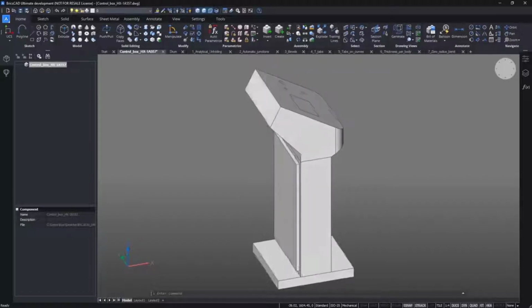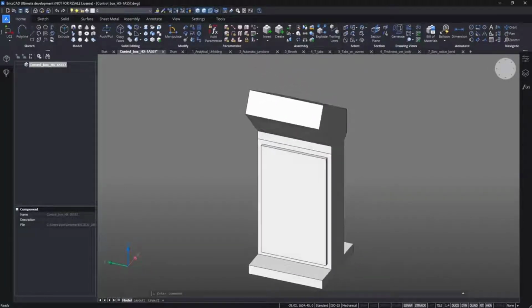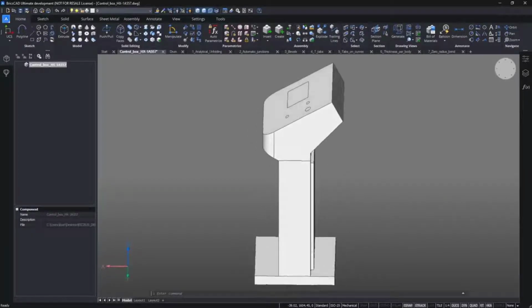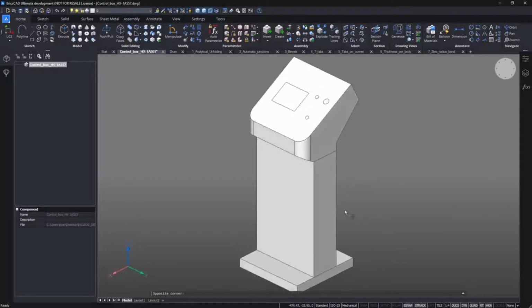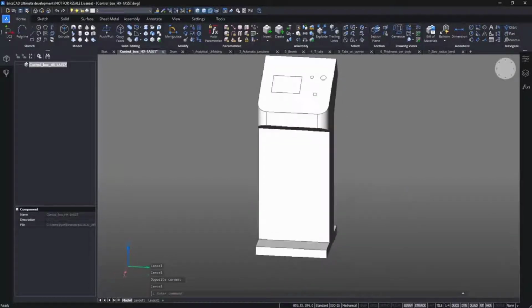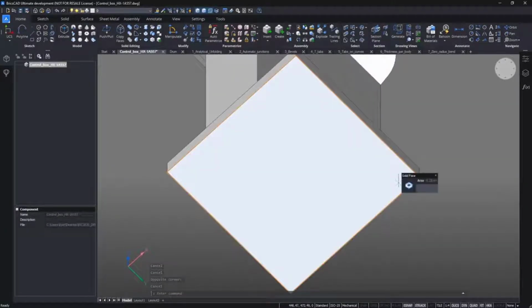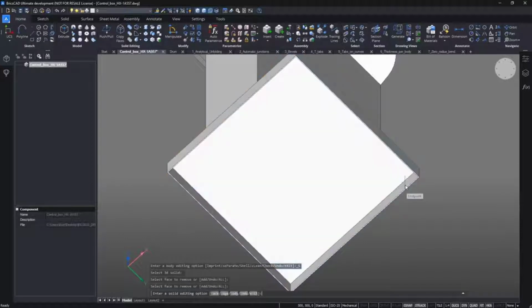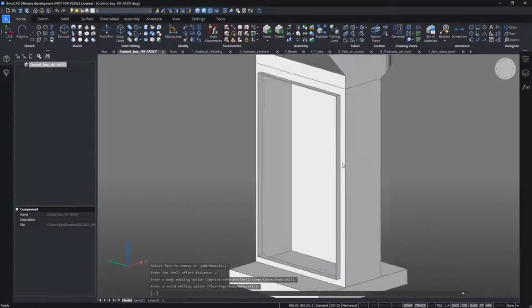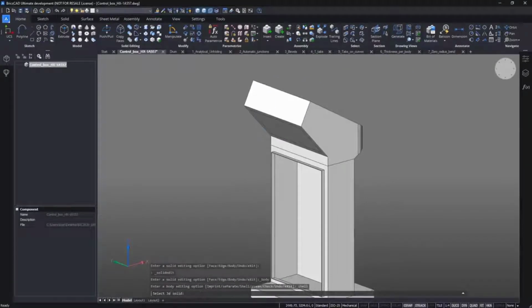In order to demonstrate the new intelligent way to create sheet metal parts from simple solids, we will use this control box, divided into three elements: bottom, middle, and top. Let's first shell those solids. Here on the bottom, here on the back, and for the top part, we have to make some necessary openings.